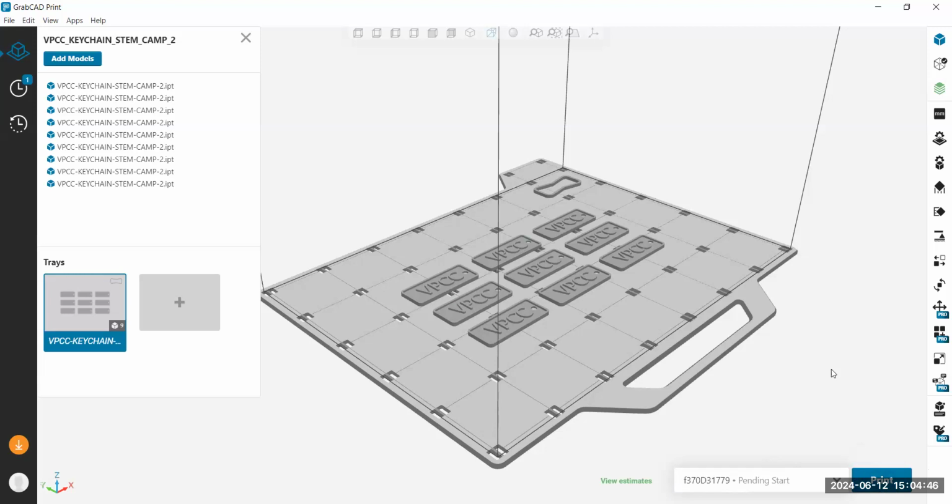So I hope that helps some. This is like step 2. The first step is you have to create the part in a CAD software package, for example, save it as an STL file, and then you bring your STL file into, this is called GrabCAD. By the way, this is free. GrabCAD software is free. You can download that at home on your computer and play around with it if you want to. So there you go. This is part 2, and the third part would be actually setting up the 3D printer to actually print out these parts.